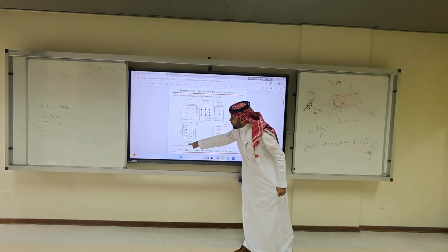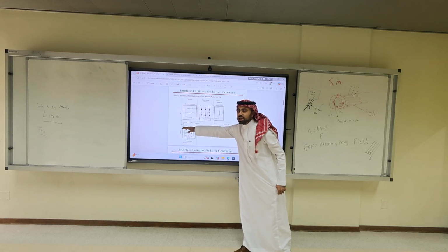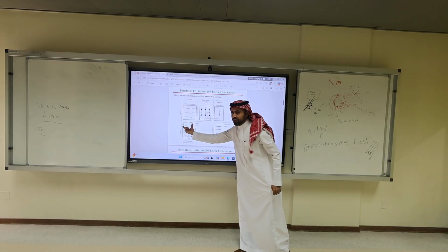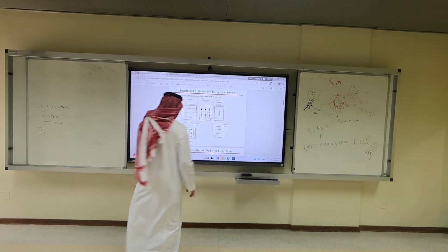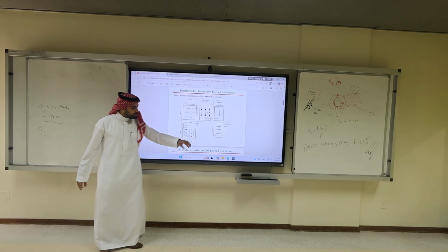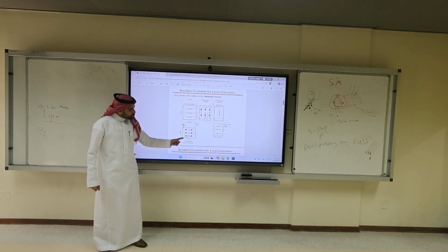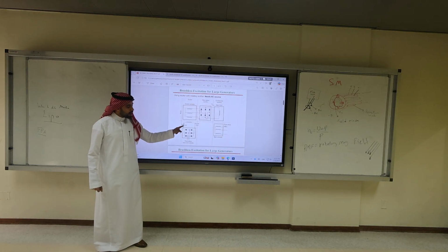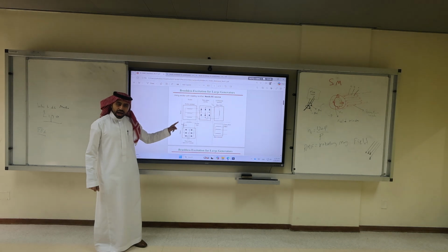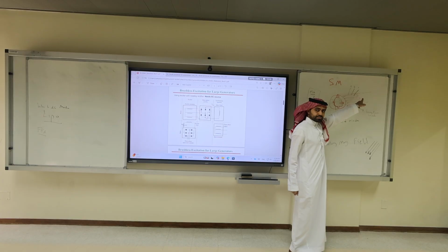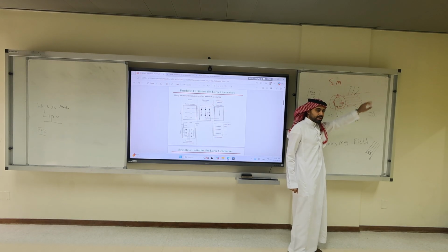So now, three-phase input low current, we're going to have here what? DC low current. And we apply it to where? To the field. Again, we apply a small three-phase low input current, 110, 120. We put it through a rectifier, and then here we have a DC. We apply this DC on the stator winding, before any movement, at the beginning.